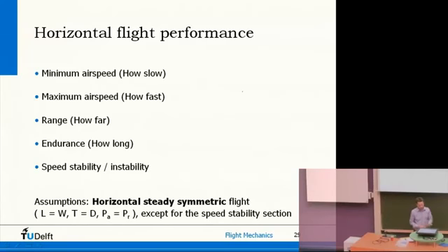In other words, since power is a force times a velocity, thrust equal to drag also means that thrust times velocity equals drag times velocity. So power available, the power you have from the engine to transport yourself, is equal to the power you require to overcome the aerodynamic drag. So that's the same equation basically.